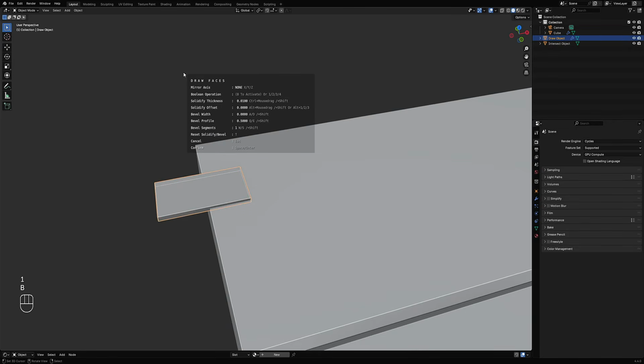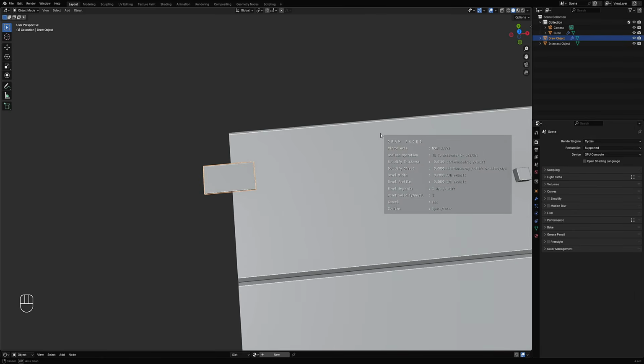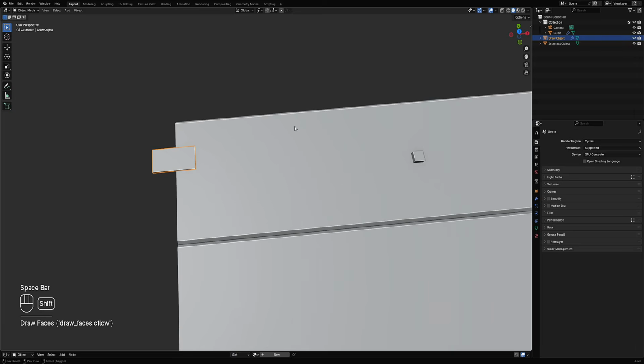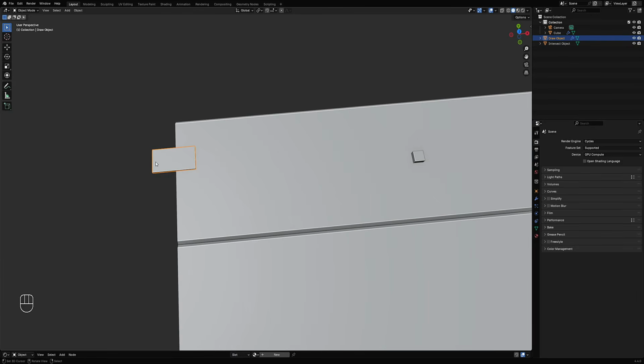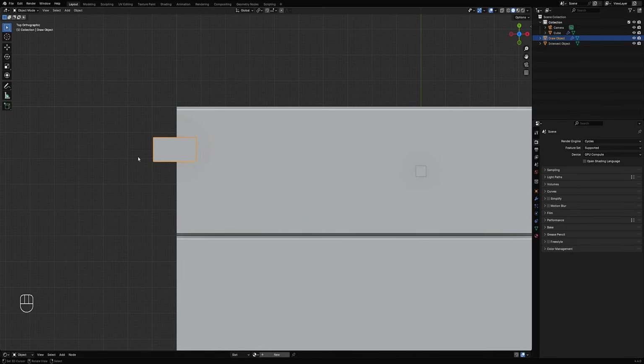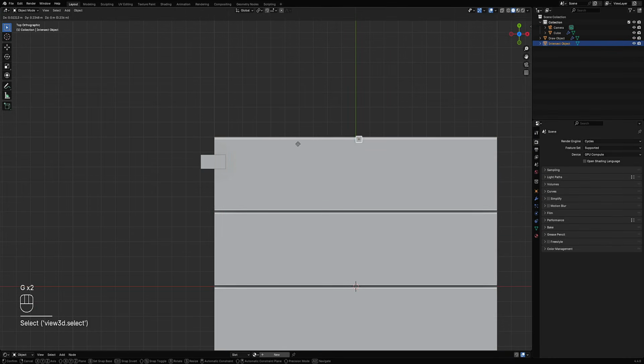So we're not going to use this, but instead we're just going to draw the faces and then use the boolean command right here, because the boolean, when drawing and using the boolean function, operates on the source object, but this will not be our source object or work object. This will be our source object for the symmetry.